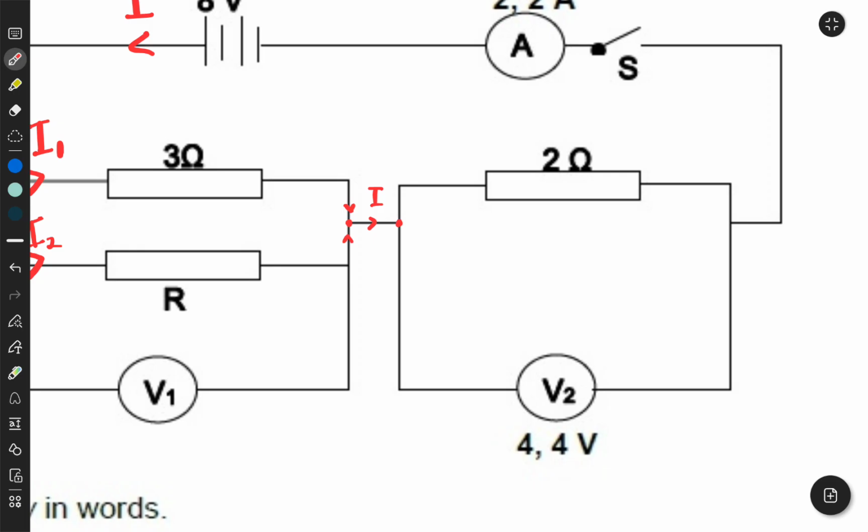of least resistance. That's why whenever we connect a voltmeter, we connect it in parallel to that resistor whose potential difference we want to measure, right? So there's nothing that will flow to that voltmeter. This is just total current flowing through the 2 ohm resistor. Then it goes all the way there, and then it recirculates again.